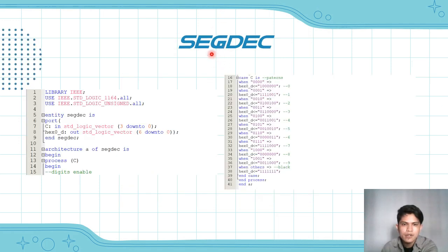Alright, for setDEC coding, it first declares the library used, and then the entity was named as setDEC, and C is declared as the input port, and H0D as the output port. The architecture was named as A, and it contains a single process that is sensitive to the changes of the C input port. The process compares the value of the input C to different case values and assigns a corresponding value to the H0D.